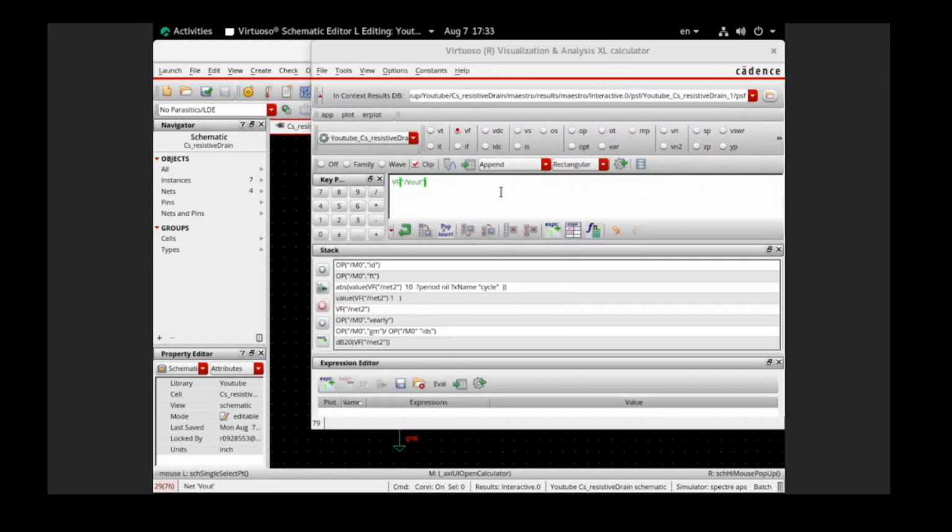If you want to know why it's relevant to the transfer function, please refer to my previous video about low pass filter and Cadence. When I do the analysis of a low pass in AC analysis or transient analysis, it will give you the idea why the AC voltage of a signal is related to the transfer function. And then this will be our transfer function. However, what do we need? We need to get the gain in dB at low frequency. So first we need to convert the